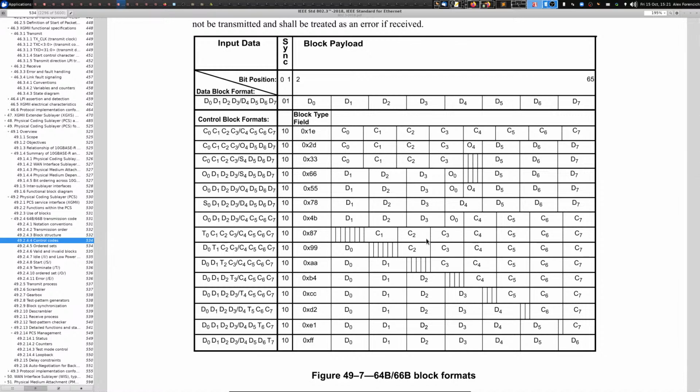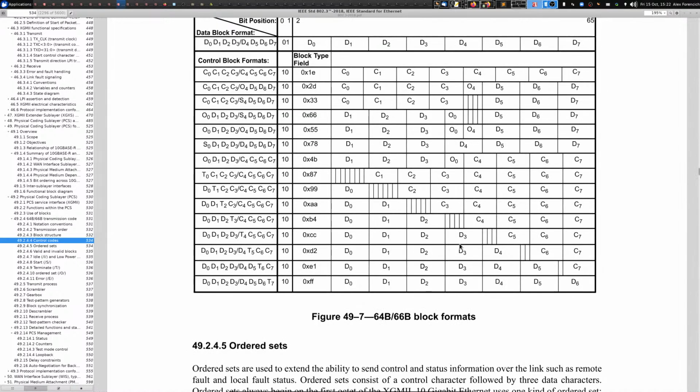And PCI Express uses something called 128B/130B, same kind of thing. But as you can see, the ratio between these two numbers gets smaller and smaller. So 8B/10B, you're adding 2 extra bits for every byte. So the overhead is pretty high, right? It's like a 20% overhead or 25% overhead, right? This is where you get differences between the reported data rate and the actual theoretically achievable data rate, or one source of that.